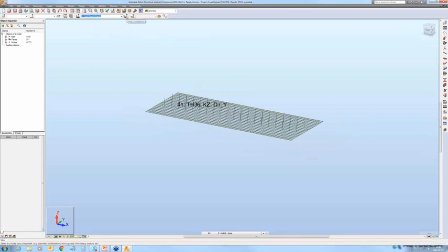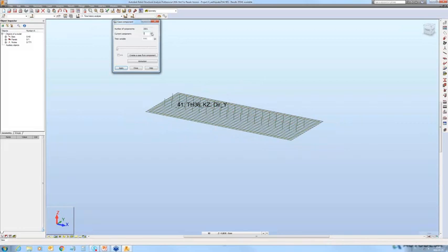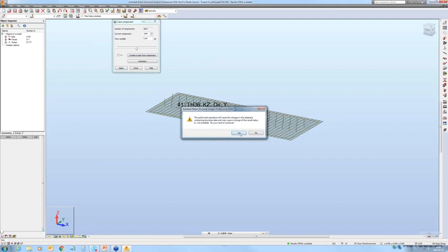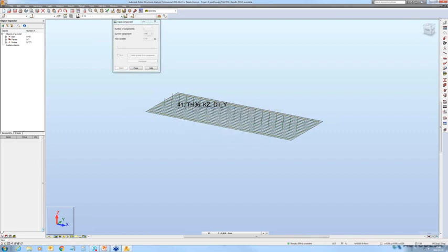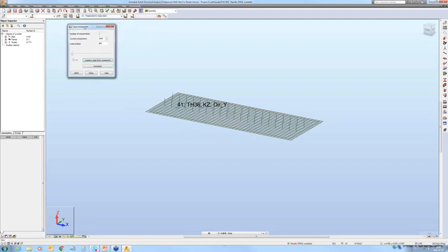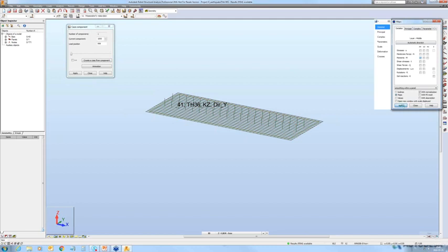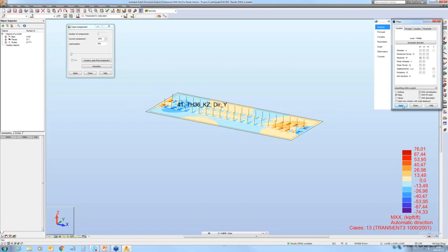And if we go here, we can see that we have a number of components, and you may actually convert one of these components into a virtual load case, as I mentioned on one of the previous slides. So if I press create case from component, you can see that we have got this load case where we haven't got the physical loads, but we may see the results as for a standard load case, for example, bending moment map. And we can use this component for design of reinforcement or for design of steel structure.